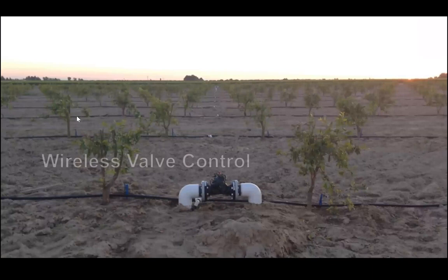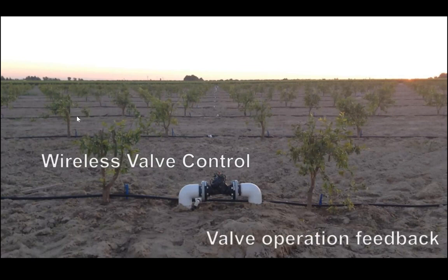And then in the field, we open and close the valves, hydraulic valves operated through solenoids, and we deploy sensors, usually pressure switches or pressure transducers, that will give us feedback of the valve operation.